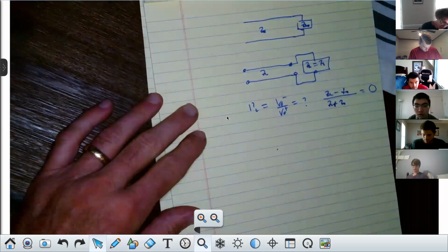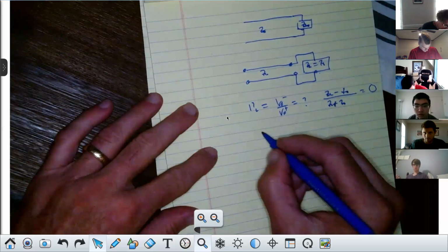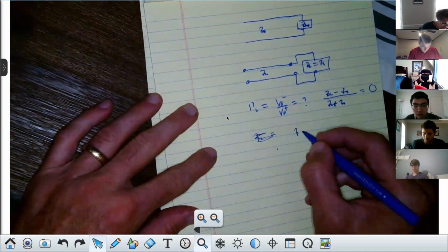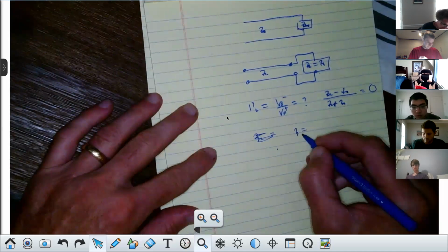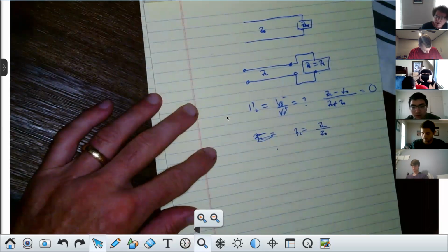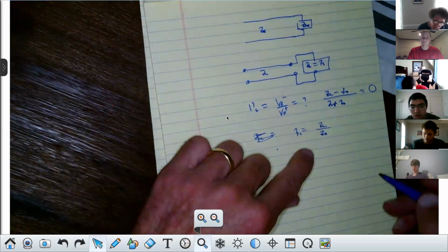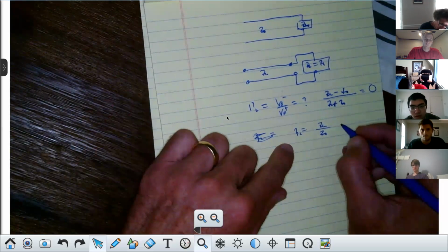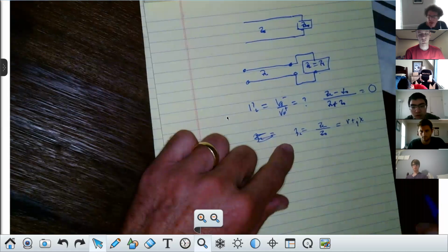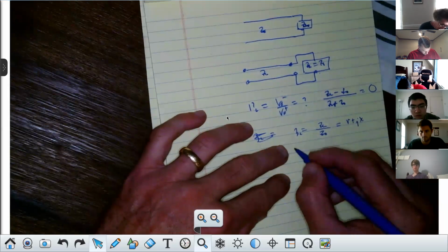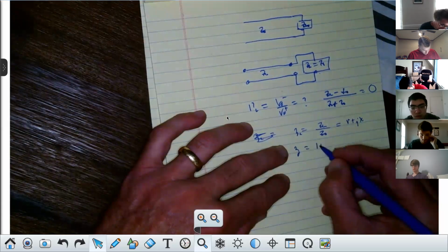Now listen, this is how we do it. When we get ZL, small z is really going to be the entry point, ZL over Z naught, right? Agreed? Yes. That's how you enter the circle. Now, I know this is going to have a real and imaginary part, R plus JX. If I can move until R is 1, I'm going to have the input impedance being 1 plus JX.